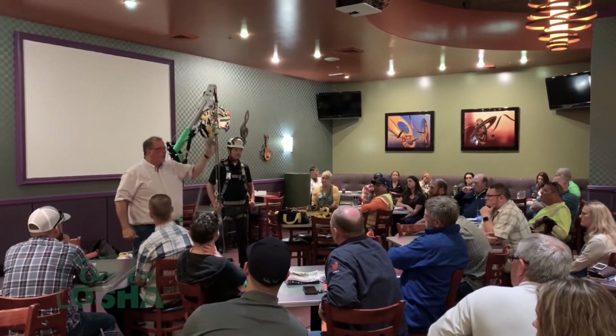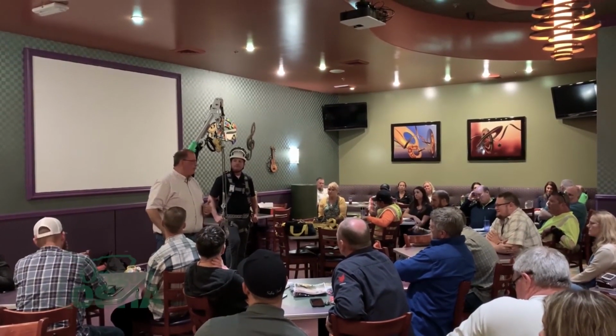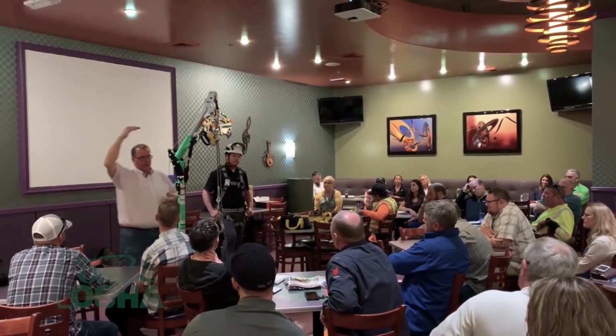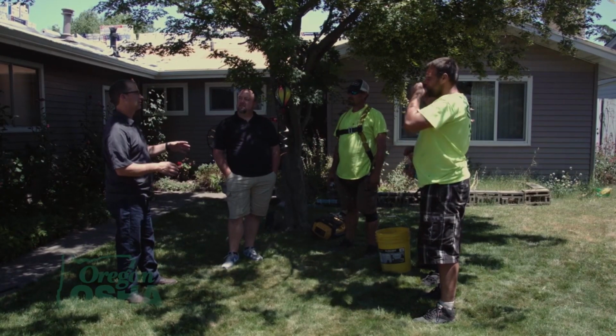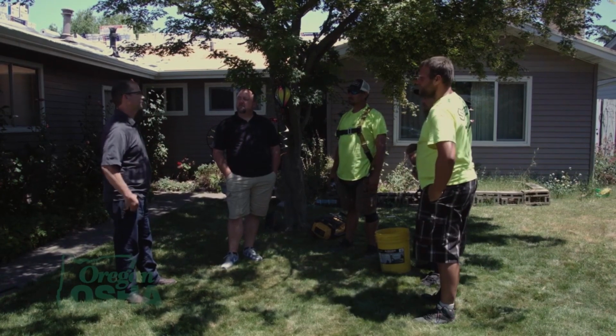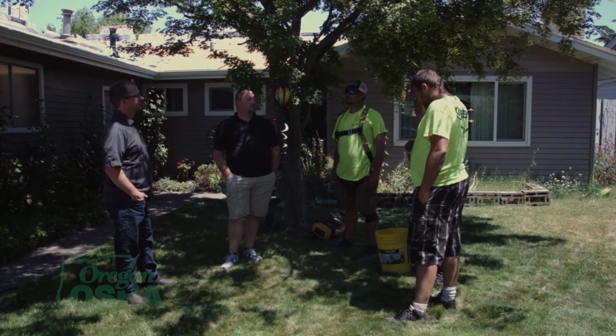And so as part of our culture, an employee gets hired, they immediately go through a fall protection training, going from requirements, this is the way the harness gets put on, this is what to look for in the rope when you hook the rope up, looking for any damage that may be done to the rope. But you can only train so much in-house. You have to do it out on the job. And so that's where our foremen finish that training and continue the training with employees, making sure that they're following that. So that training happens in the shop, and then it also happens out in the field.